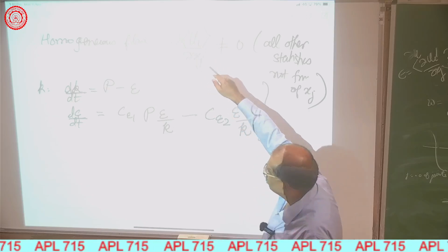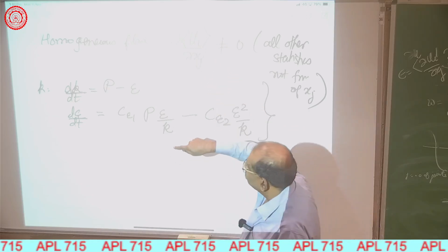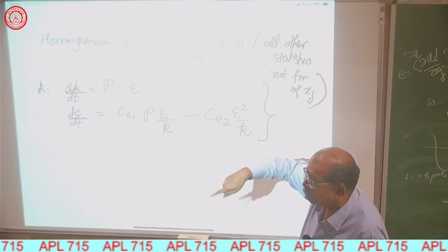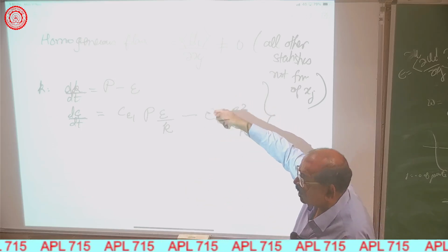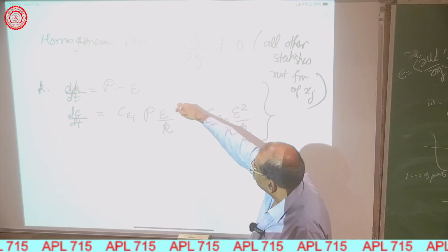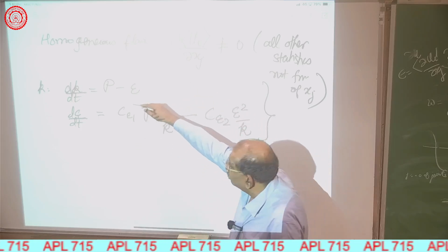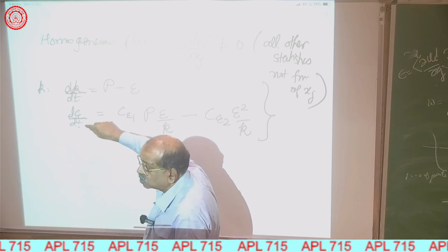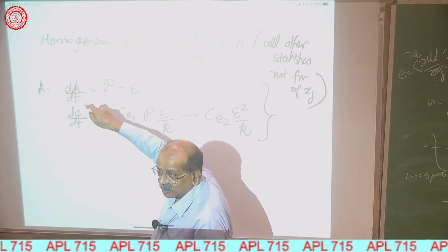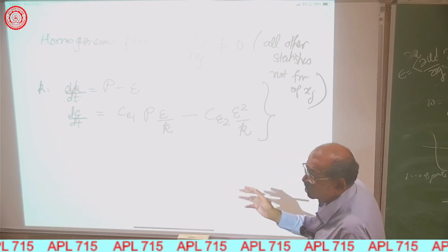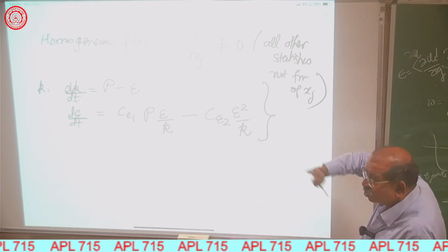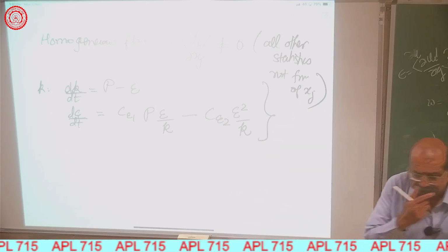There's this thing in the convective term, you have mean of uj d by dxj of k or epsilon, so they will also be 0, because k and epsilon, meanwhile realize that they are also turbulence quantities. They are means, they are not fluctuations. So they also don't change with space. So this is the form you will get.